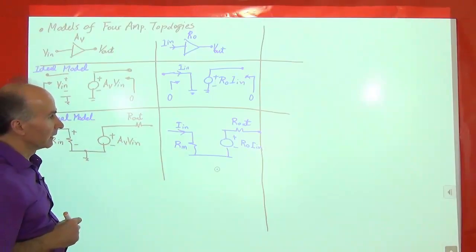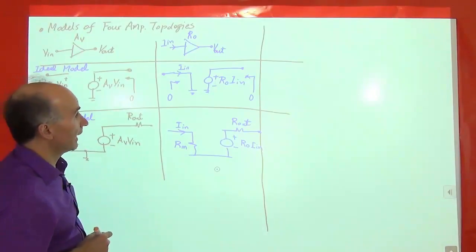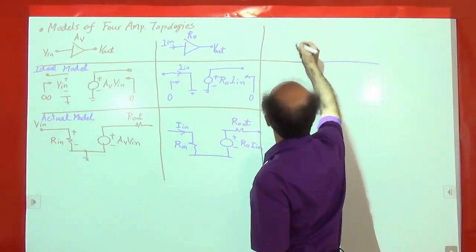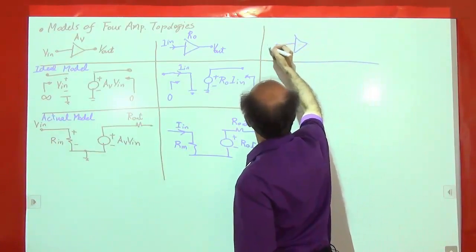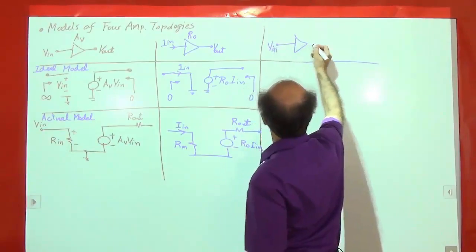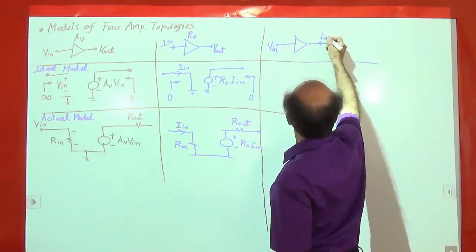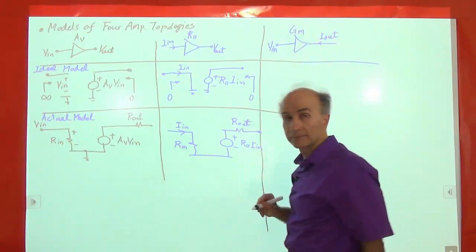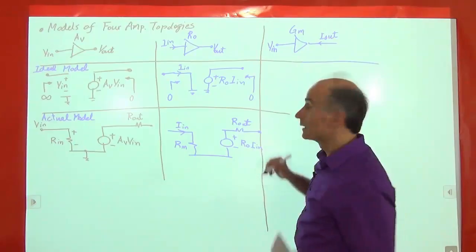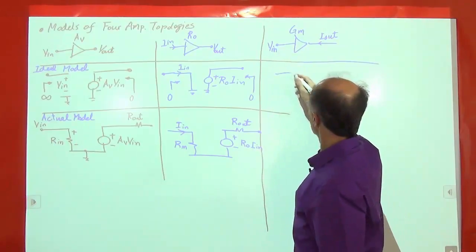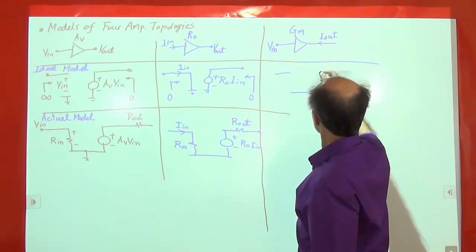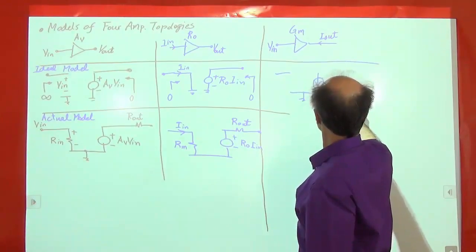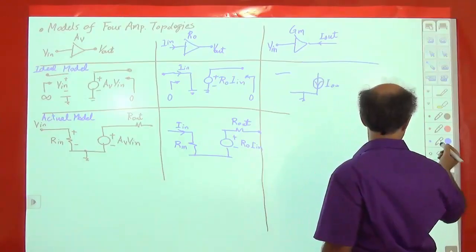Okay, all right. We have 2 more amplifiers to go. So let's do that. The next amplifier is a transconductance amplifier. It senses a voltage, gives us a current, and the gain is denoted by GM. All right, so ideally, we are sensing a voltage, so we have an infinite input impedance. We are generating a current, so we have a current of I out, which is equal to how much?